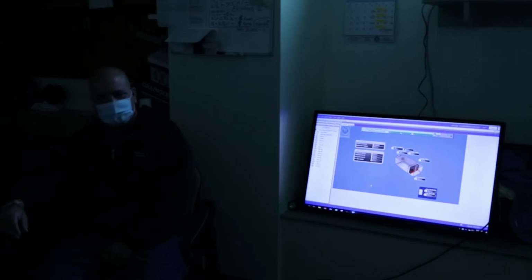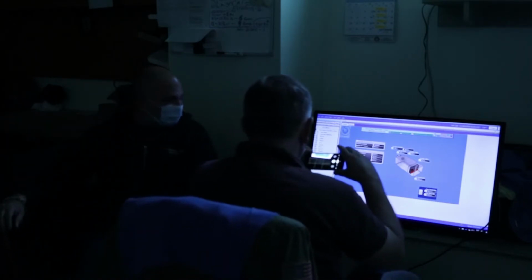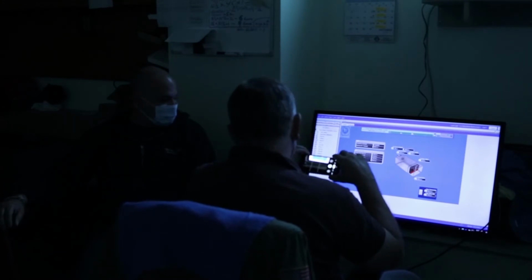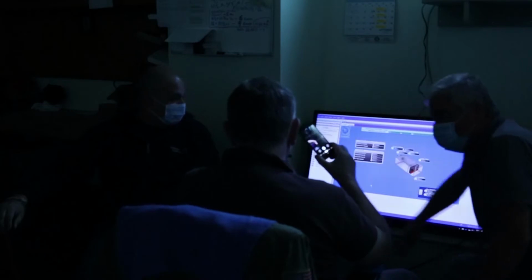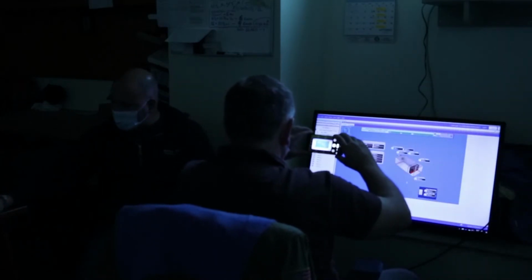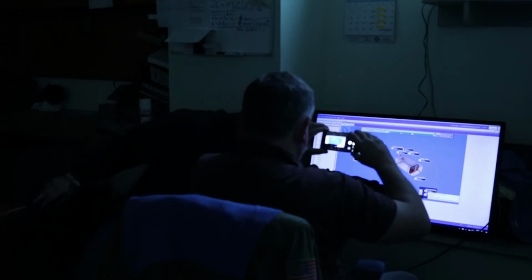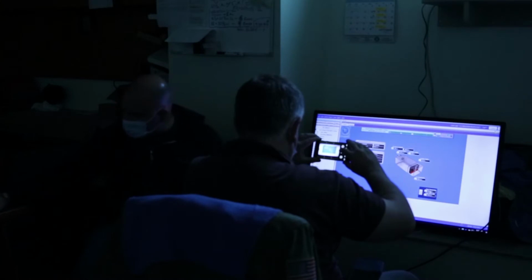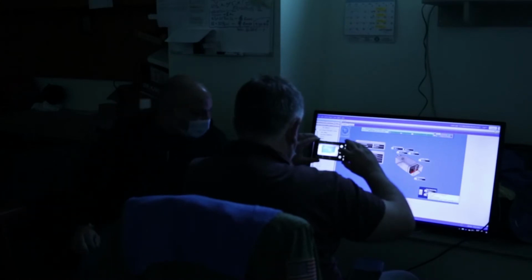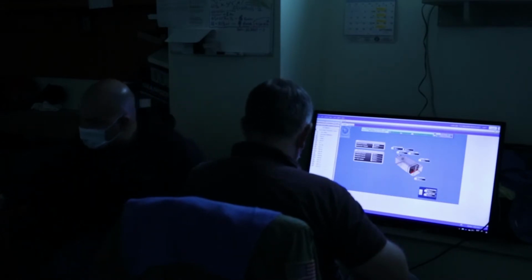Actually, I think I'm ready already. From the beginning, when we just start with a trend, for example, and we can do the same for alarms, right? Well, I'm going to show you. What we're going to do is highlight the point and figure out where it is. Just put the cursor over the point, and that tells us the path. So we see NAE 5 FC2, its location, the VAV box. Now we go over to the tree.